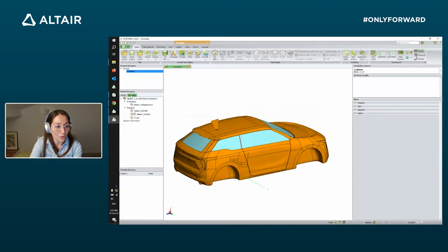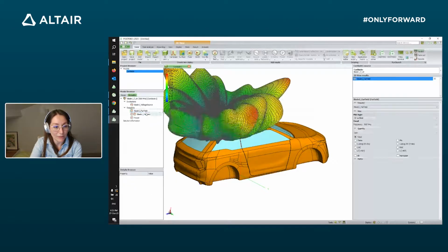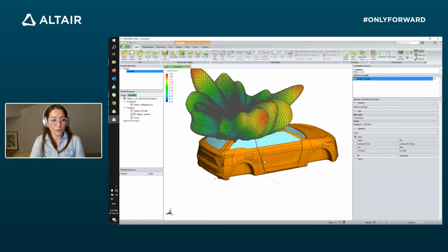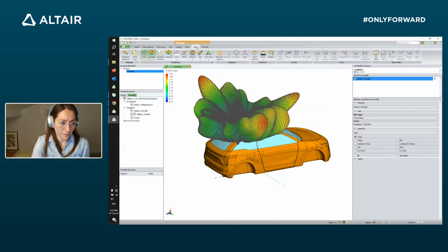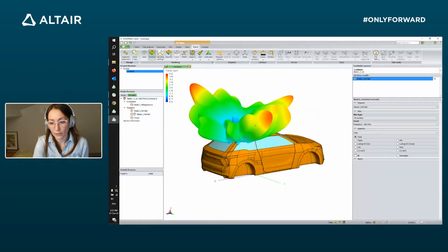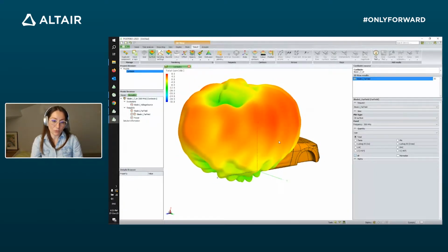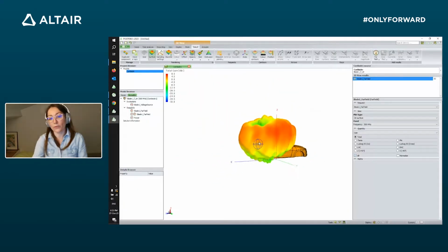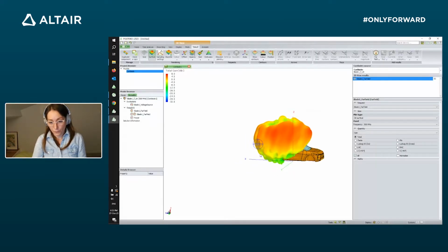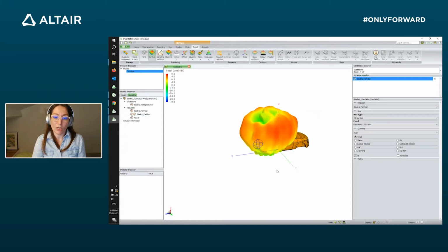And when we go under the model browser, the results tab, I will choose the far field and add it to the current 3D view. Let's remove the grid, keeping just the surface view, and we can toggle to dB view of ours. So this is basically the far field of the blade antenna due to its position on the car.